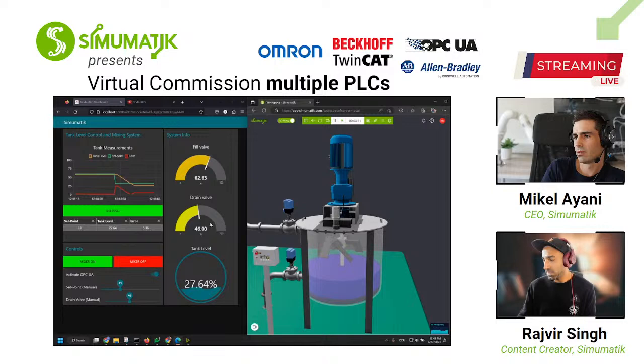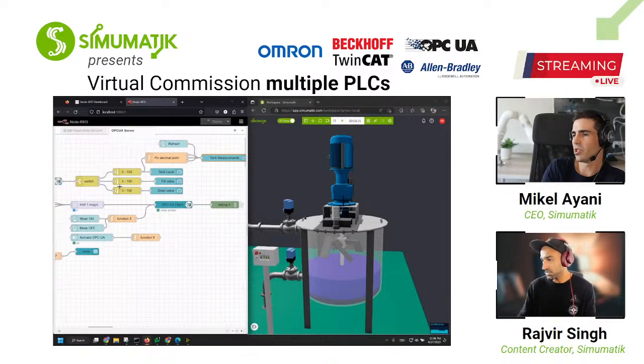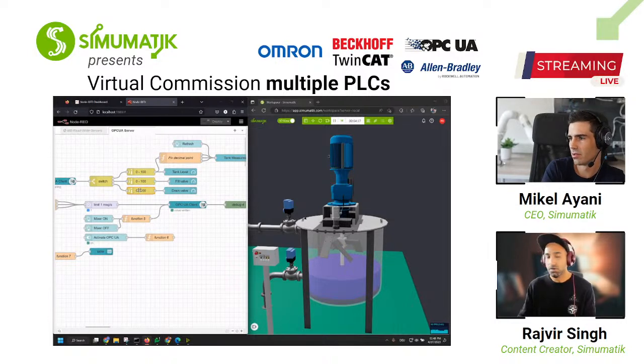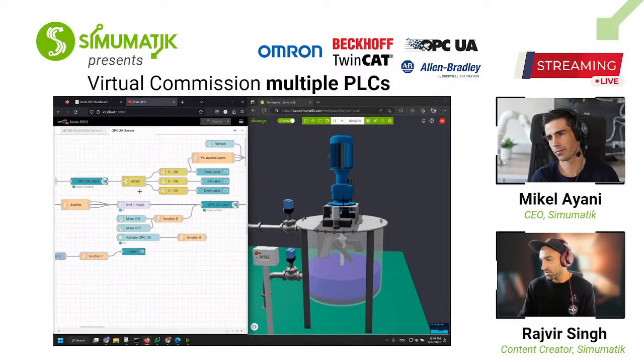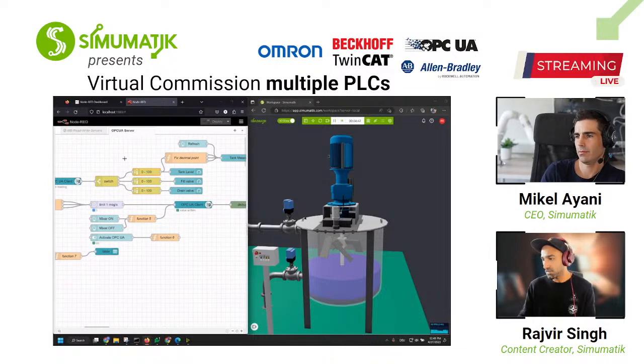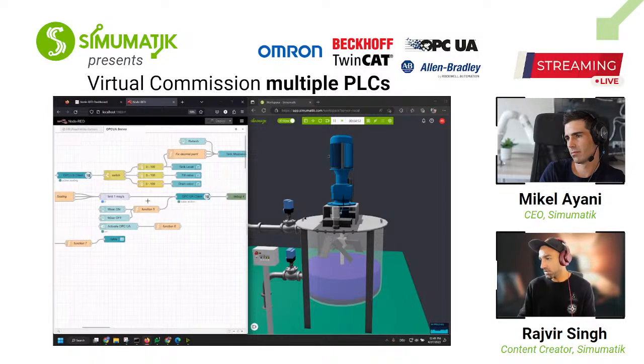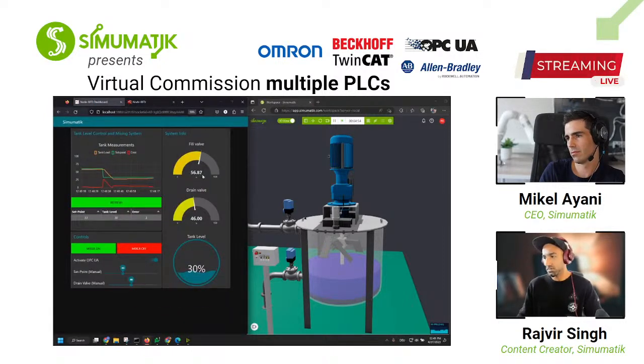And remember, the information coming from OPC UA has to be scaled because I'm getting the value in terms of voltage. So I convert the voltage to 16-bit data. Then I scale that to 0 to 100. So you have to do a little bit of scaling in that to get your values in the range of 0 to 100%, which is here.